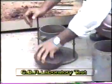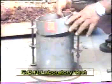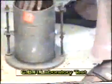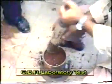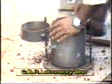The spacer disc is placed at the bottom of the mold and filter paper over it. The processed sample is placed over this. The soil is compacted in 3 layers with 56 blows for each layer of 50 mm thick. The collar is removed and excess soil at top is removed and leveled with the straight edge.